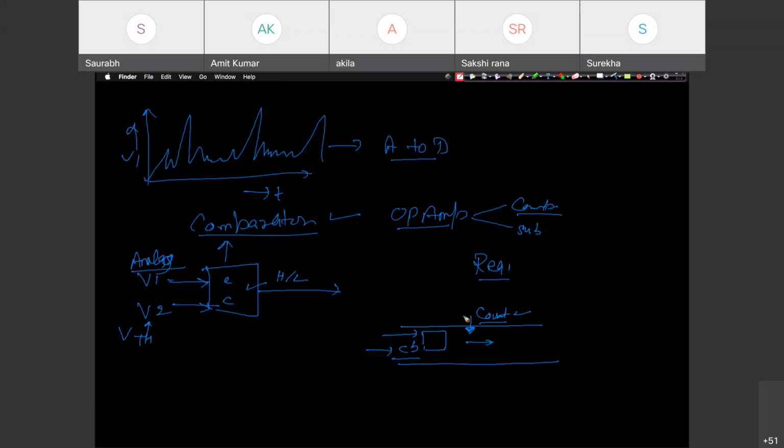So here one single sensor will just sense whether the object is available or not. This is object detection without a camera, without artificial intelligence or machine learning algorithms, just with hardware, with one single sensor, to check whether an object is coming along the conveyor belt from the A side to the B side. So we have to count. The object can be detected based on distance: suppose the sensor is here, and we check the distance. If no object is there, the distance will be more. If the distance is less, then an object has passed.